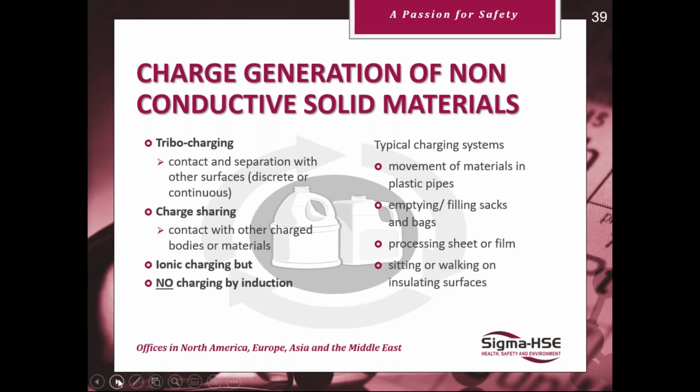You cannot charge an insulator by induction. Typical charging systems include movement of materials in plastic pipes, emptying or filling of sacks and bags, and processing sheet or film, especially materials like acetates, for instance, and sitting or walking on insulated surfaces.